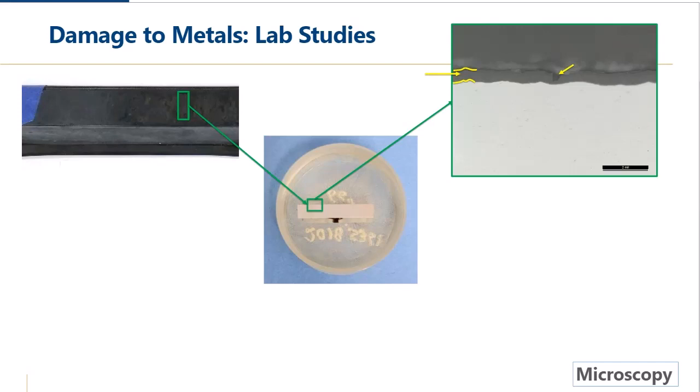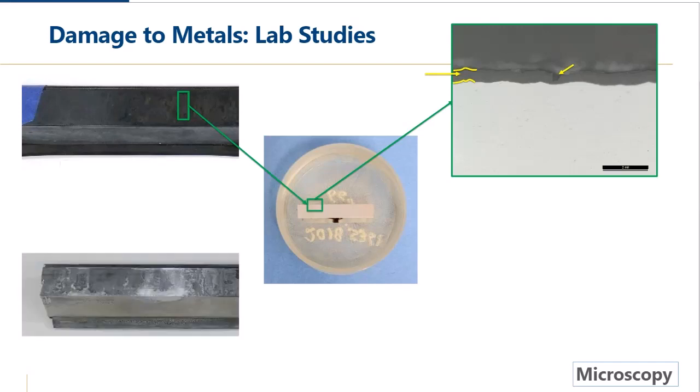Now we compare that to a more severely degraded sample where we have some evidence of the aluminum coming through and much more distress. Now here we're going to do the same polished cross-section procedure, but here the image I'm going to show you is of the entire thickness of the aluminum because the anodic layer is gone in the area we were examining.